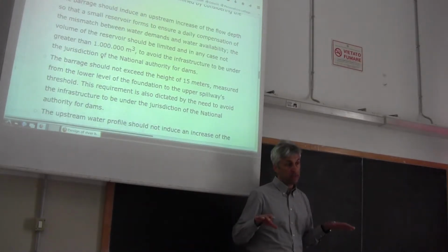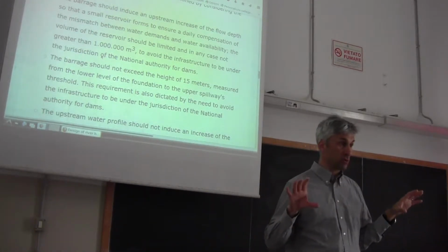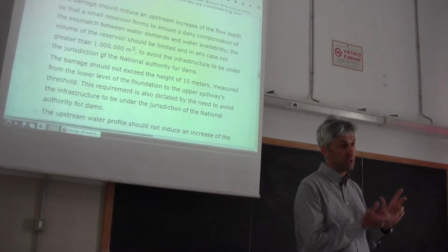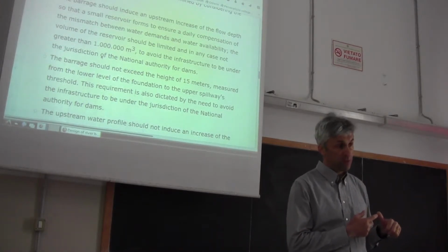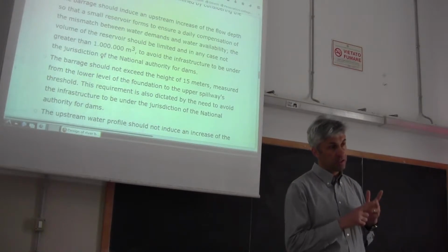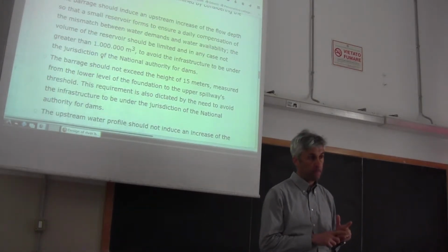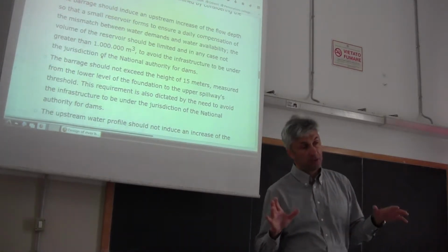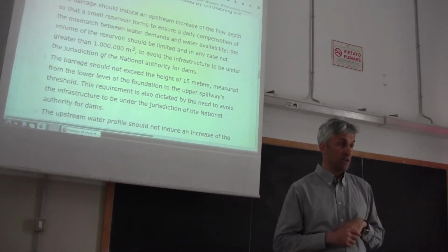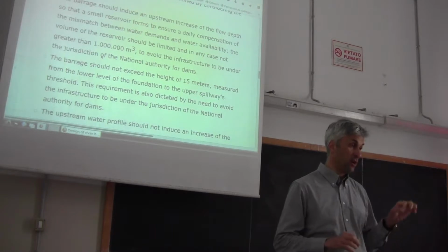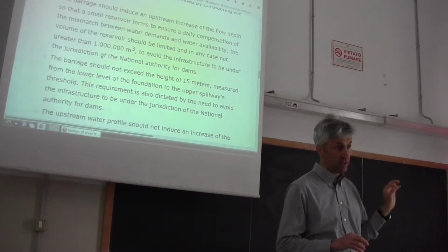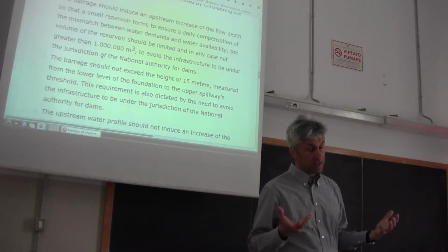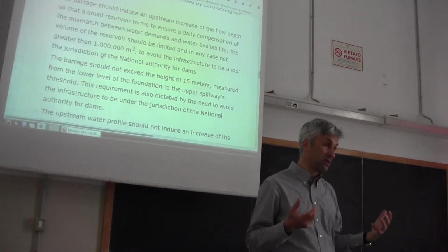Once that you determine the overall elevation of the structure, the next question, which is very relevant, is to determine the elevation of the spillways. We talked about 3 spillways: the environmental flow spillway, the diversion spillway, and the main spillway. And these are not placed at the same elevation, of course. These are placed at different elevations. And the lowest one, the lowest in terms of elevation spillway, is the environmental flow spillway. Why is that? Because to the lowest spillway you give the priority.